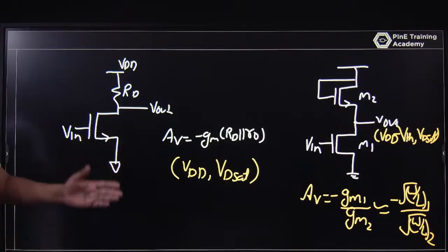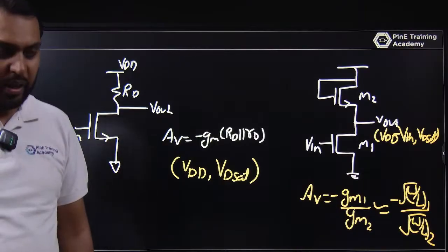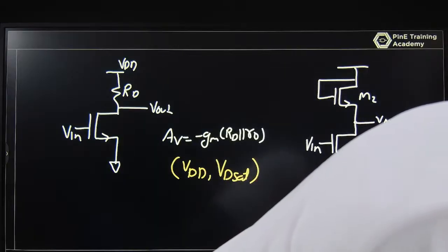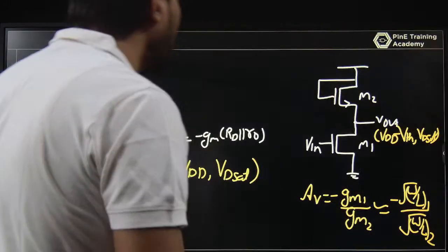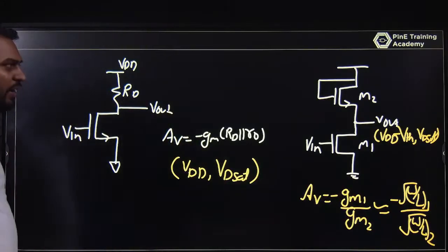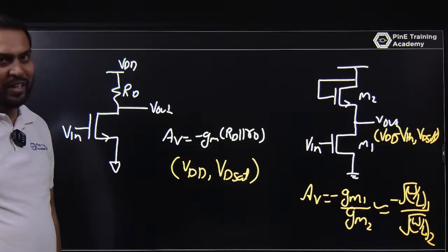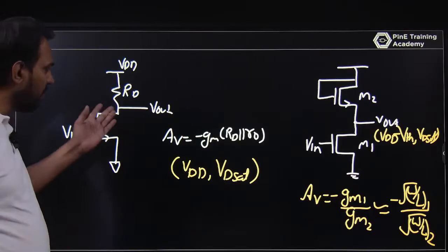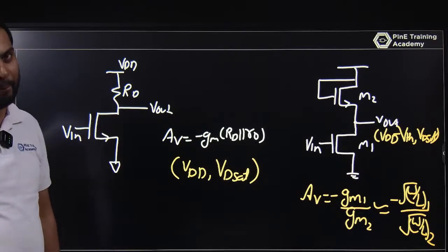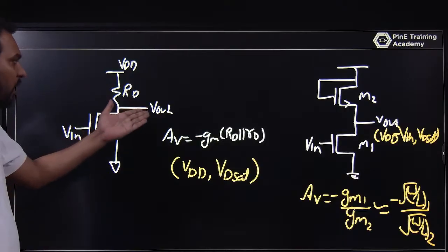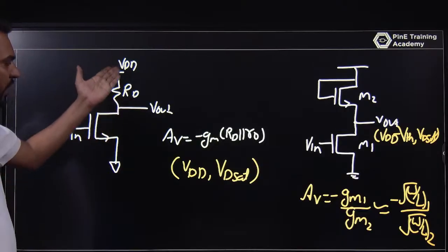So if you are using a diode connected based circuit, if that dimension is the same, it acts like a buffer. Why would it be buffered here? How will it look like a buffer? No, it's not like a buffer, it will behave like an inverter here. If you are providing the input as 0, then Vout is what? The current is 0, so it is VDD.